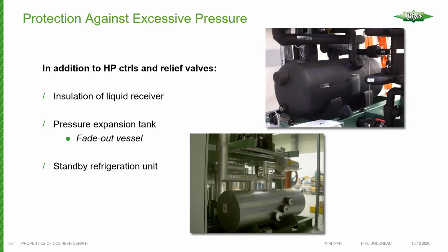Generally, that receiver tank is going to be held at a saturation temperature of anywhere from 30 to 40 degrees Fahrenheit, maybe a little bit outside that range, but generally those are the types of temperatures that we're holding the tanks at. And over time, the pressure can increase. So by insulating it, this limits the amount of heat that transfers into that vessel.